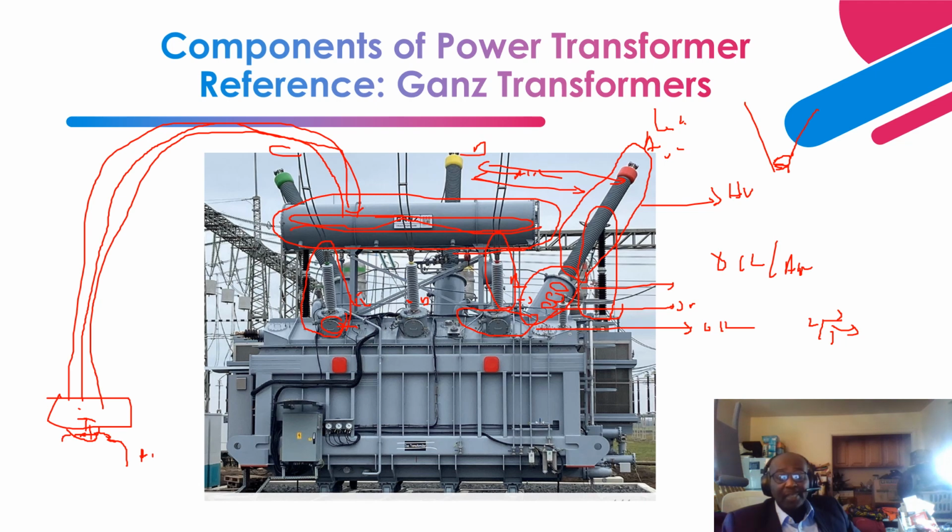Inside the surge arrestor are metal oxide varistors, a non-linear semiconductor. During normal operation, the surge arrestor offers a high impedance to the ground plane, and only leakage current flows. But when you have a lightning impulse surge, due to the high voltage, it changes from a high impedance connection to a low impedance connection. It clips the voltage, then discharges the current to ground.